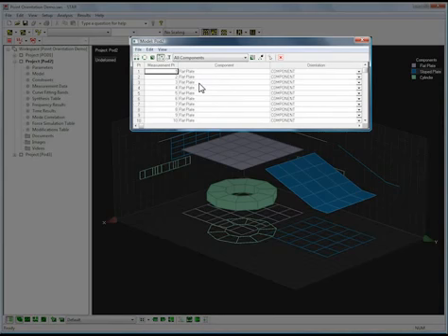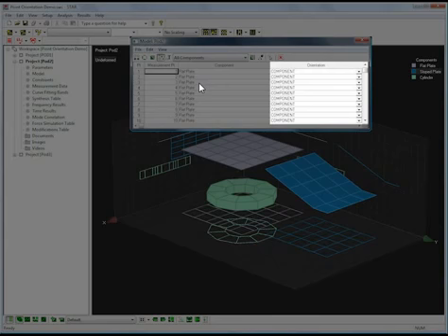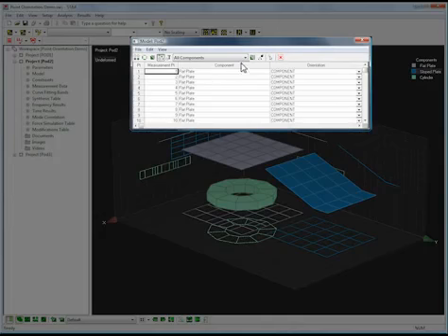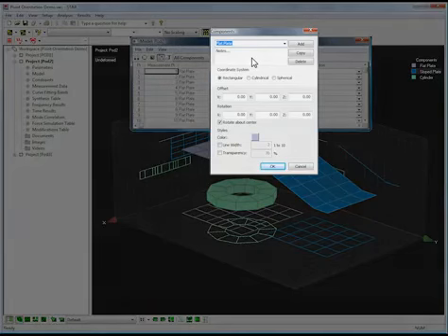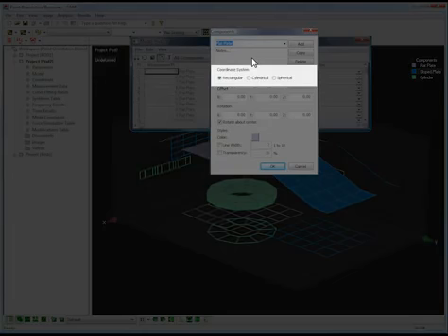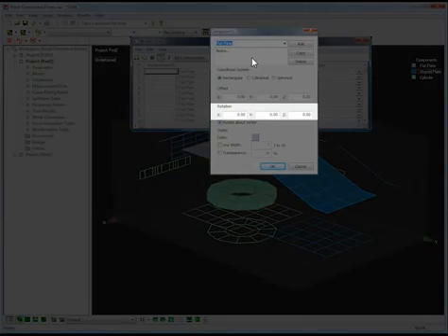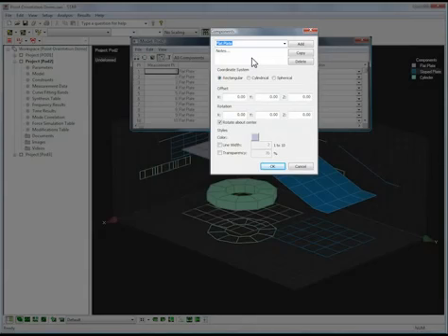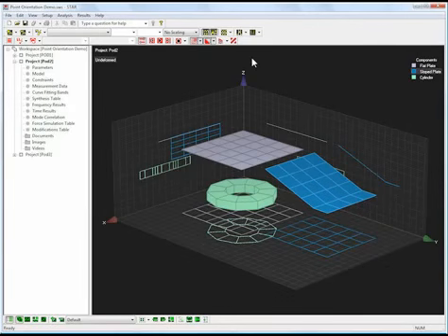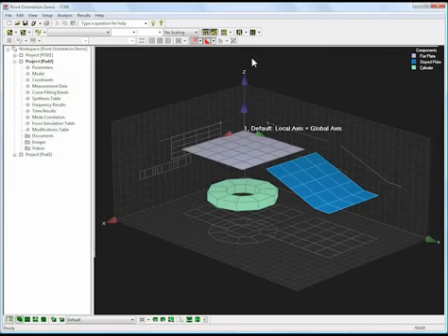For each point, there are 3 main types of local axis: Model, Component and User-defined. The default is Component. When Component is selected, the local point axis will depend on the coordinate system and any rotation applied to the component. The default settings are a rectangular coordinate system and a 0 rotation, so the component axis will match the model axis, i.e. the global axis.